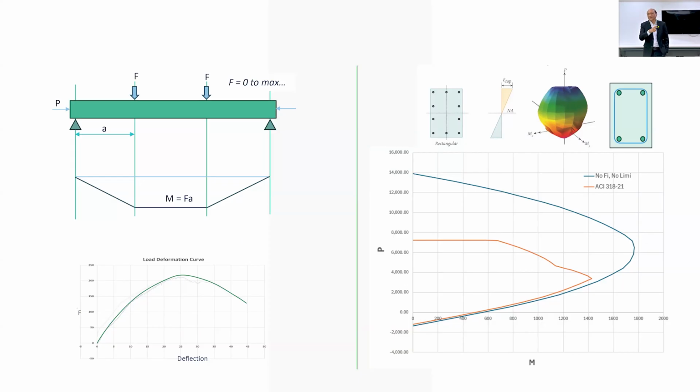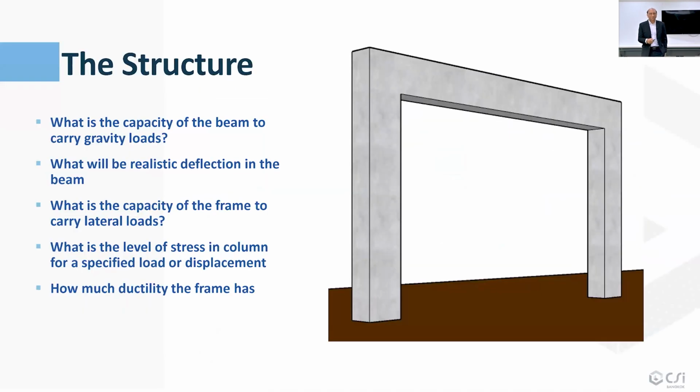So we can't really get correlation between real load and the capacity diagram that we have here. Theoretically, it may be here at one point, but actually the load can vary along this one at any location. Moment can vary from 0 to any moment, and all of them will exist until the beam really breaks down, assuming that it doesn't fail in shear first.